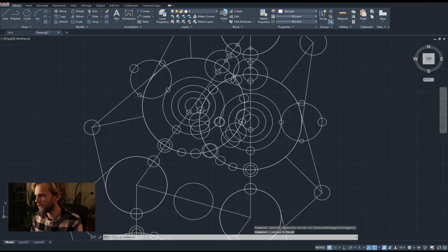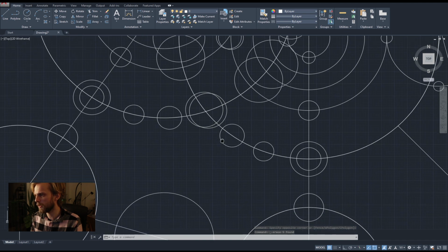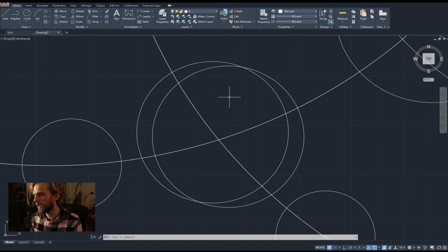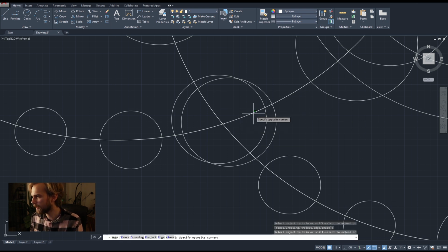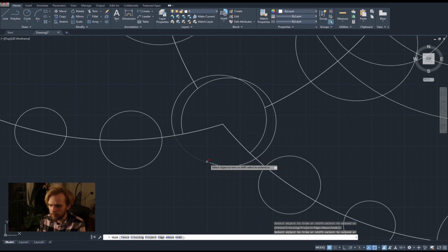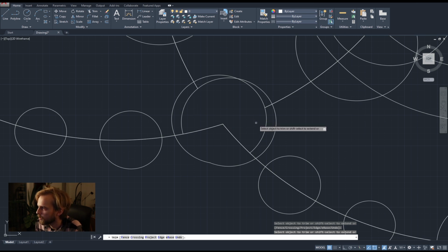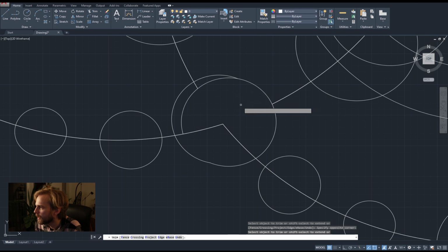So if I were to look at the more complex example, let's say I want to clean this up, I can say tr, enter, enter, and then I can just kind of go to town and keep deleting this. And I'll purposely make a mistake, or not a mistake, but I'll do a thing that always happens, and I'll keep kind of going here and trimming away all of these segments. And at a certain point, I can't anymore. Well, I can still trim away this one, I think, yes.